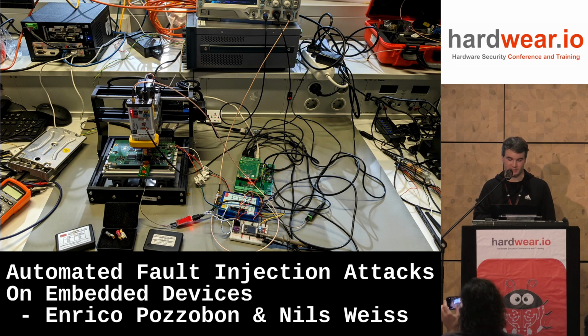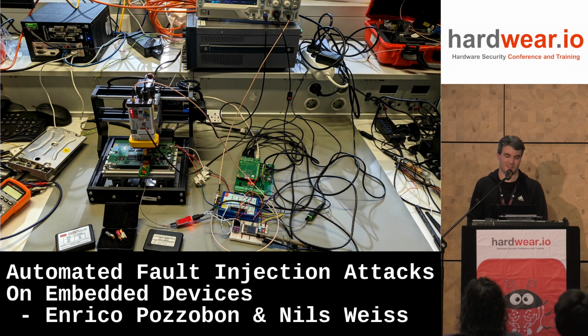Then we have a ChipSHOUTER, which can be moved by a CNC machine. And all of this is quite cheap. So I think that the cost of the full setup was around 5,000 euros. And the most expensive part here was the ChipSHOUTER, by far. Later we tried to replace the ChipSHOUTER with the PicoEMP, but that one needs a little bit more voltage, I think. It doesn't emit faults that are intense enough for now. But yeah, it can definitely be made cheaper.